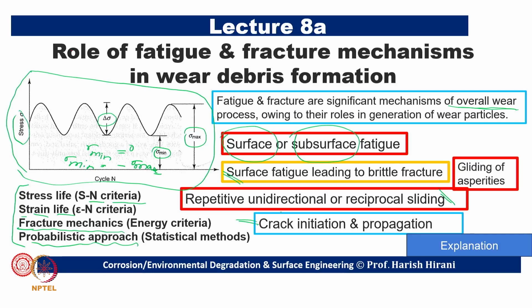The question comes, what is a crack initiation? We have deliberated this in one of our earlier lectures, but in my view, a crack is always there in a material. It can be the boundaries, different kinds of crystallization, or polycrystallization, or when we are trying to alloy materials and combine different materials, cracks will be there, inherently. The only question is, what is the size of a crack?